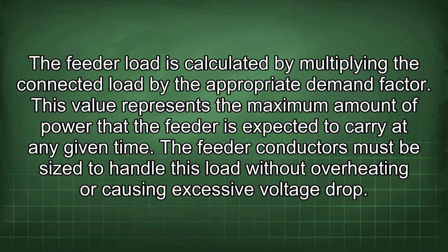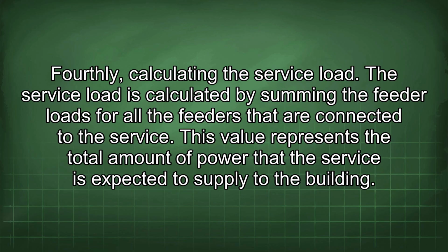The feeder load is calculated by multiplying the connected load by the appropriate demand factor. This value represents the maximum amount of power that the feeder is expected to carry at any given time. The feeder conductors must be sized to handle this load without overheating or causing excessive voltage drop. Fourthly, calculating the service load.